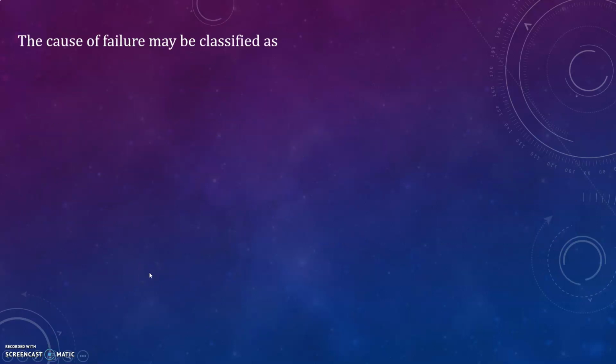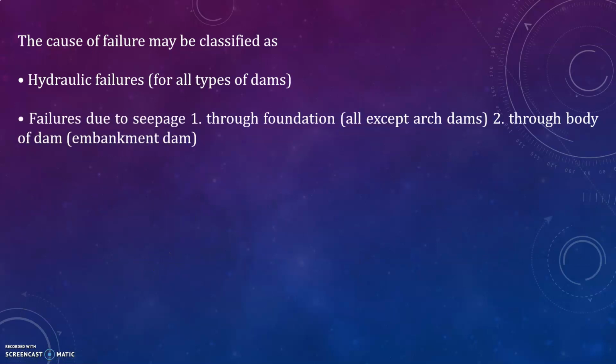Okay, so these causes of failure may be classified as hydraulic failures, which is common for all types of dams, and also the failure due to seepage. So these are the main two types of failures. The first one is hydraulic failure. This is common for all types of dams, and the second one is failure due to seepage. There are again two types: through foundation, which can be observed in all types of dams except arch dams, and also through the body of the dam. This is mainly in embankment dams or earth dams.